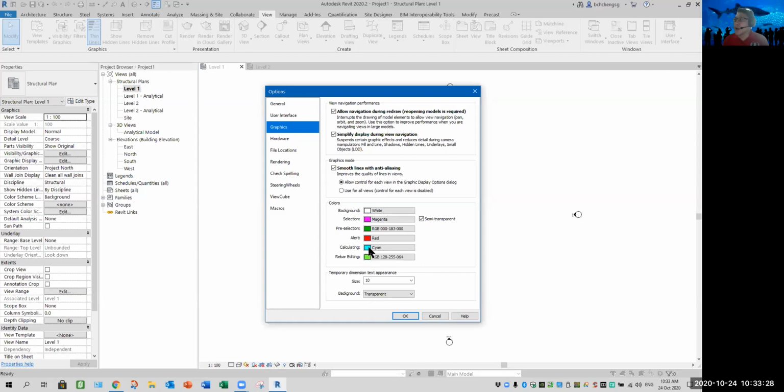For Revit Architecture, they need to calculate for evacuation, so they need to calculate the travel distance from room to exit, which means your main door. For structure, the calculations could be your rebar loading, your structural loading, dead load, and live load. So they need all this representation. You can see rebar is all here, so these two are more for that kind of thing.